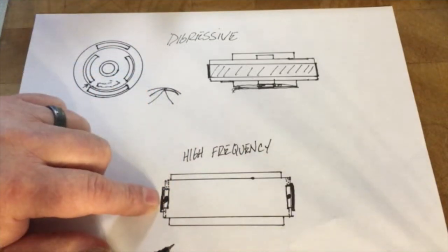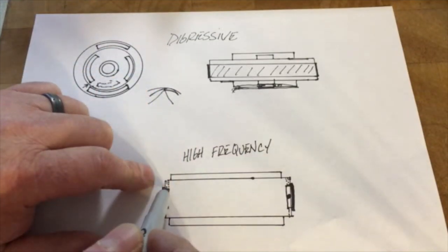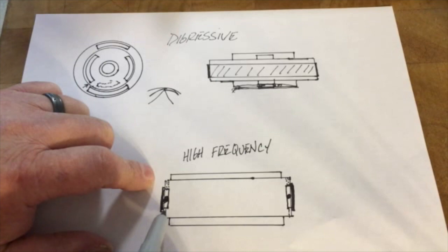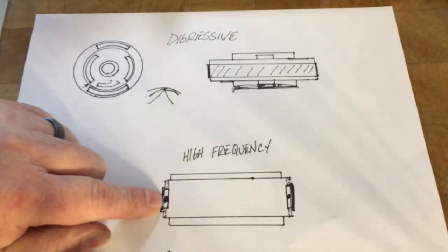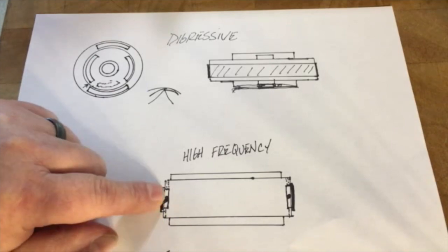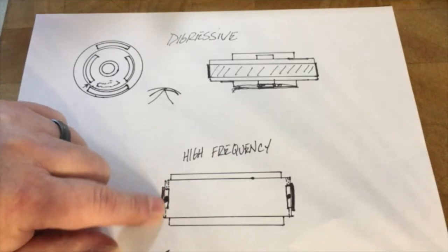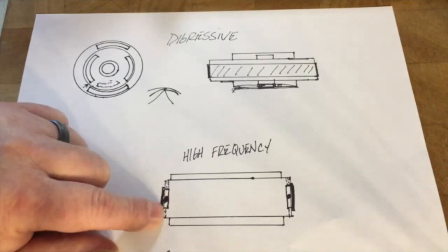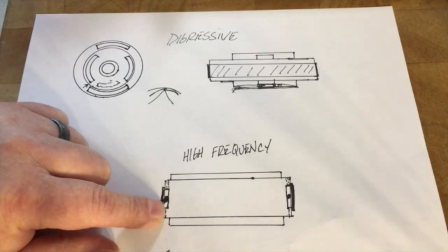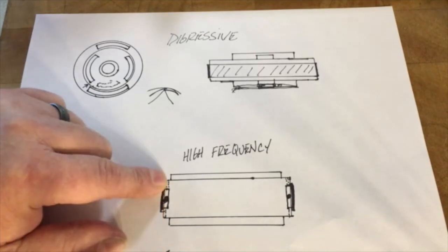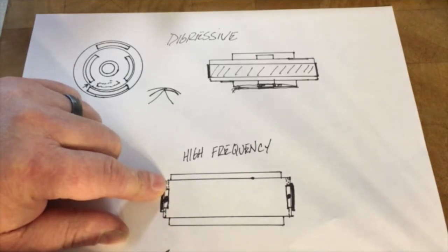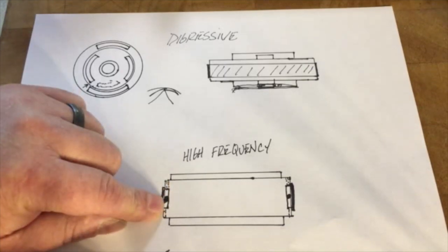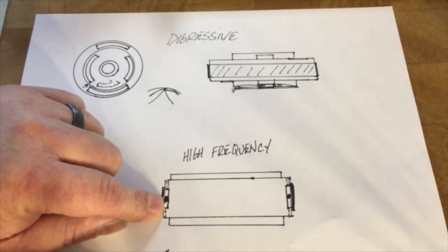So what Öhlins did is they have little bleed orifices here, and as your shock is changing direction, this O-ring would flop, and the distance that this O-ring would flop was to take out the high frequency bind and give a little bit of bleed, but then it would flop up against the top and close off the holes, or flop down and close off the holes against the bottom.